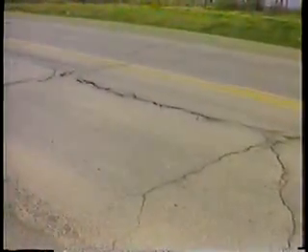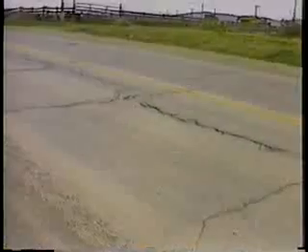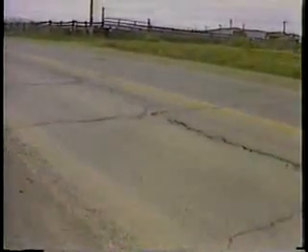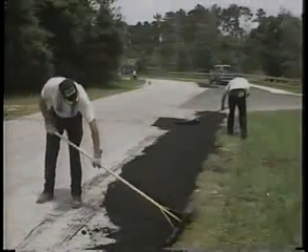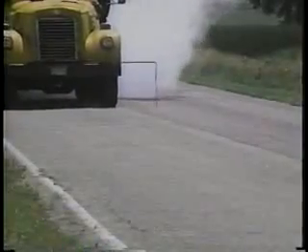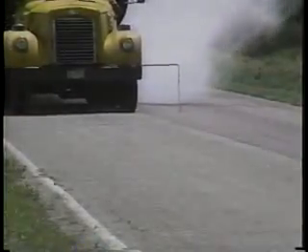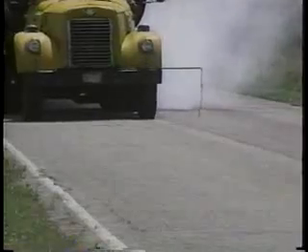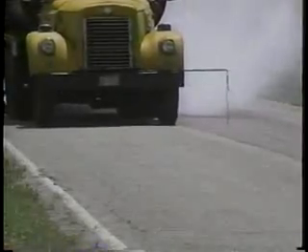Chip seals are not recommended for treating potholes, rutting, bleeding, corrugations, or severe or extensive cracks. Even when such problems are isolated, they must be repaired before chip sealing. Otherwise, they'll just reappear on the new surface. On the other hand, chip seals are effective in treating pavements that are raveling and are oxidized and weathered.